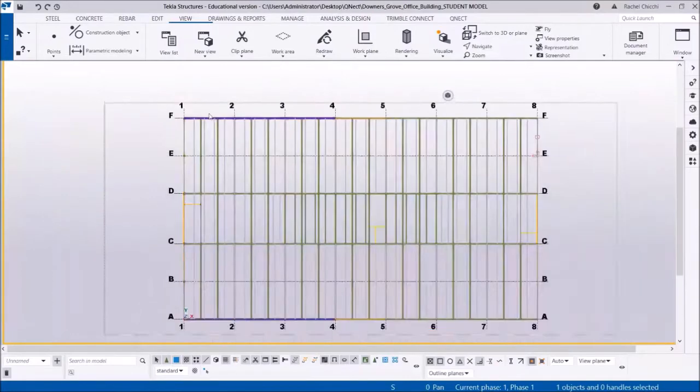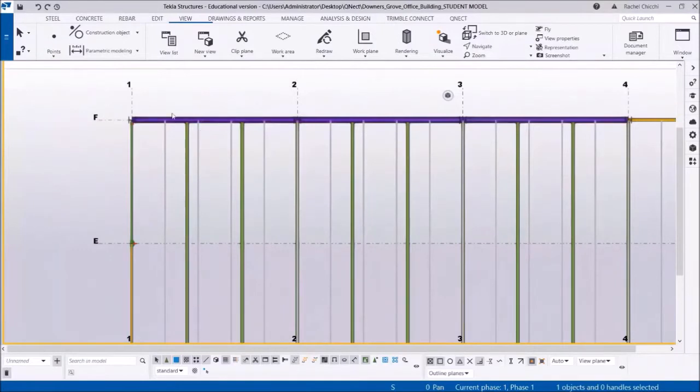So for example, if we look at this gray framing coming into this purple framing, you can see that they meet at a 90-degree angle. There isn't some kind of other skew, other angle besides 90-degree angles. Orthogonal framing means you're framing things in at 90-degree angles. It may not always be possible to lay your system in a uniform and orthogonal way, but efforts should be made early on when coordinating with the architect to try to achieve this whenever possible.